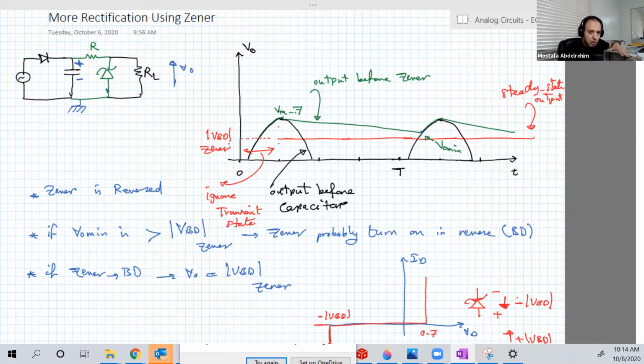That's not a very perfect solution, because as you see here, we reduced the sum of the power. So the input power is actually something like this. That's the input. But let's assume our input now is the voltage at the capacitor. So the previous voltage without a Zener was this green signal. So we just cut off, or clip it, at V breakdown.